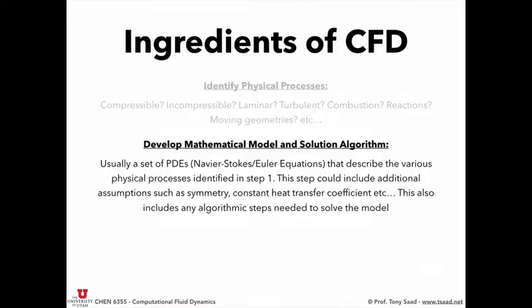Okay. Next, in light of your physical processes, you want to develop a mathematical model for these processes and a solution algorithm. For CFD, we know those are going to be the gas dynamics equations. They are the general equations that govern a fluid flow. They have three momentum equations, a mass conservation equation, and an energy equation. And anything beyond that depends on your physical process. If you have reactions, you have to add equations for your reactions.